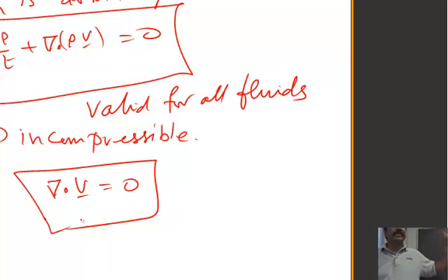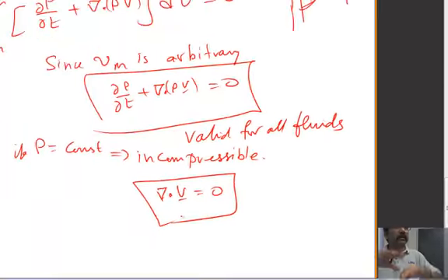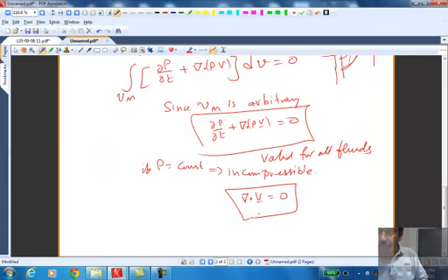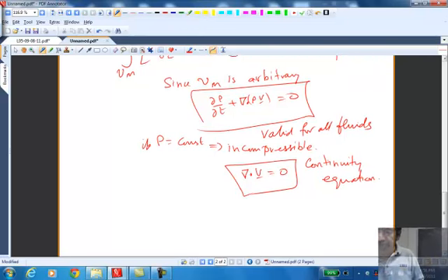This is why we introduced this idea of a gradient and divergence, etc. Now we can talk about a physically meaningful equation, which is the continuity equation. If del dot v is 0, that means the continuity equation is satisfied by that three-dimensional velocity field. This is a very important equation called the continuity equation. Sometimes it's called the divergence-free condition on the flow field. Any questions?